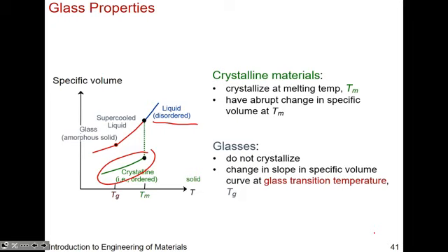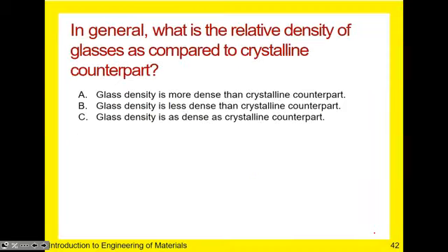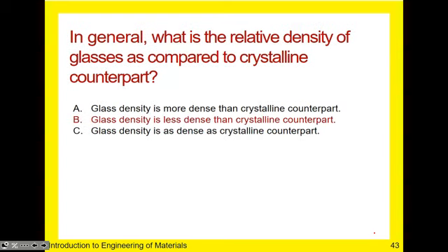And if you work in polymers already, this is probably not the first time you've heard of the term TG. You deal a lot with this, and you look at the phase transition in polymers, and you look at the TG of different polymers. Okay, so we will, oh, actually, I think this is actually not loaded. So we'll just discuss it as well. But I've gone over this point that glass is less dense. It takes up more volume than its crystalline counterpart, okay?